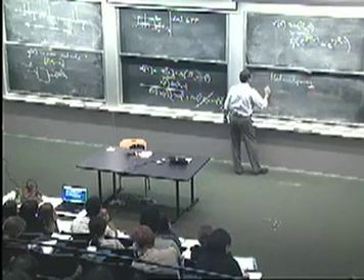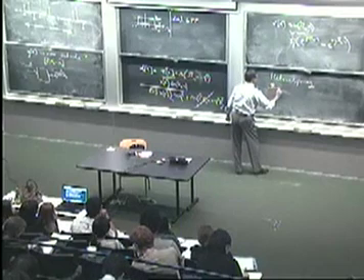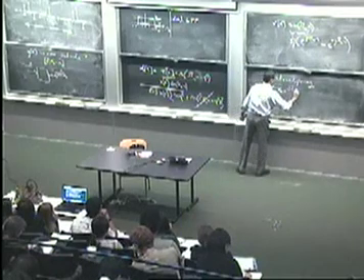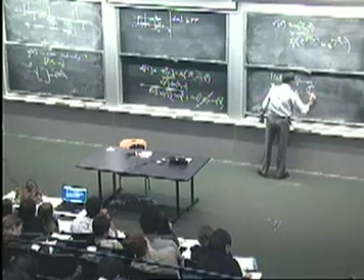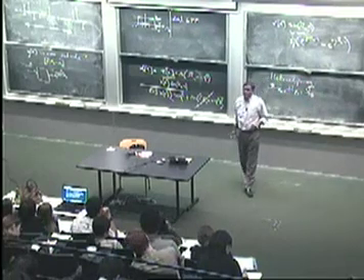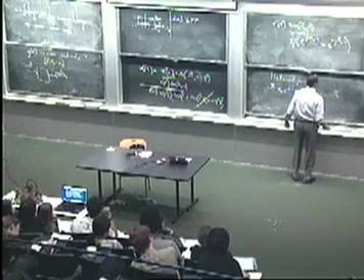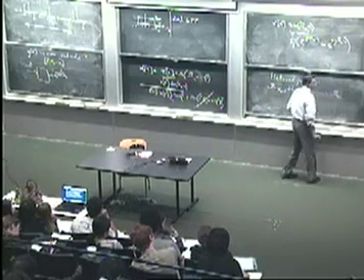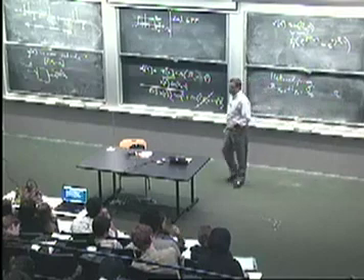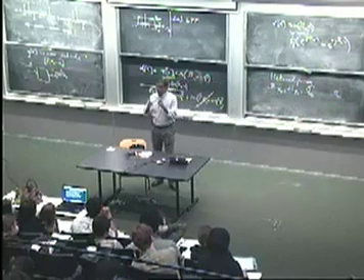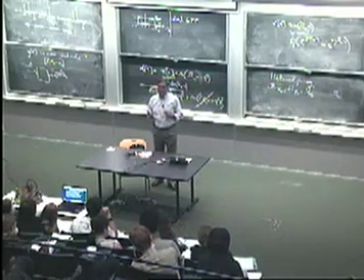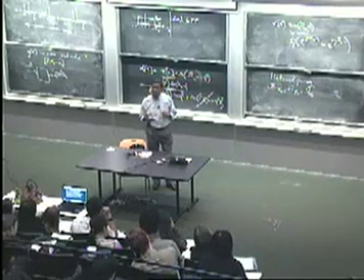Okay, so if you've got frequencies omega red, omega blue, omega green in the signal that you're receiving, and you multiply this with some local sinusoid of frequency omega naught, where will your various spectra be centered in the result?